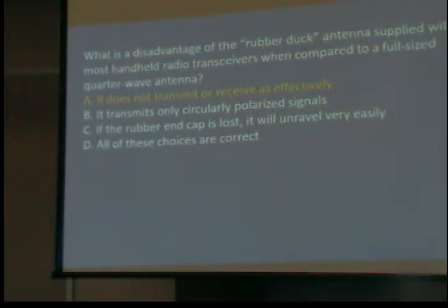Now, I will tell you a little trick. We have learned that 60 feet with 3 feet hanging down on each end still works. It's down a little bit, but not much. And what do you have, a 2-story house? It's a ranch, but it's a walkout basement, so half of it's a second story. So you have relatively nice height, not the recommended height, but there ain't big dipoles that are at the recommended height anyway.